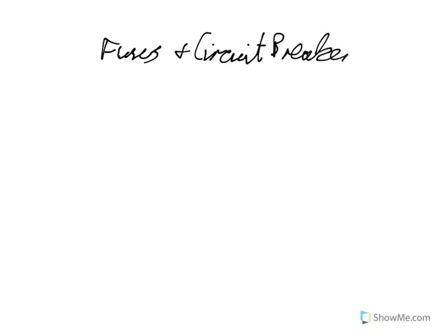Well, we use things called fuses, although not so much fuses these days, but circuit breakers. A fuse is just a bit of wire that melts if the current through it is too big. A circuit breaker is an electromagnetic device that opens up if the current's too much.